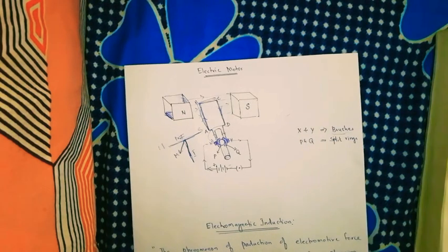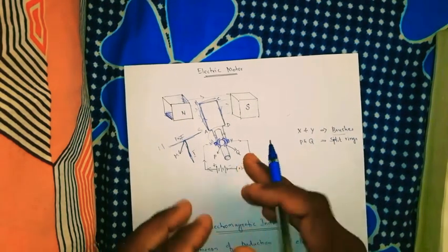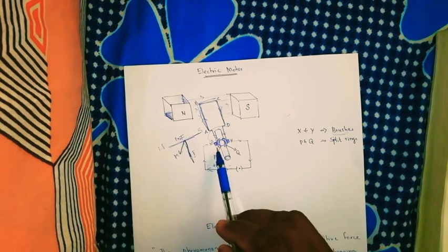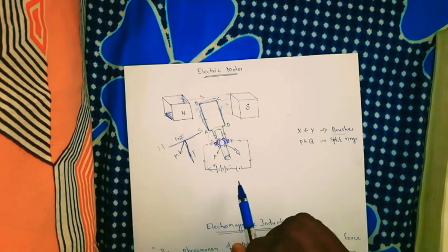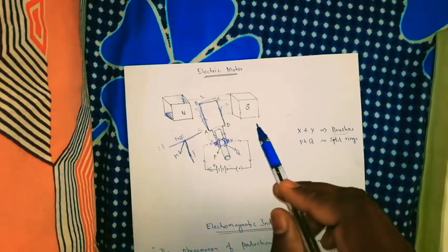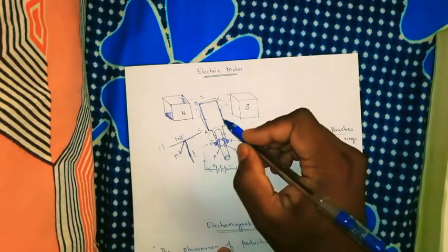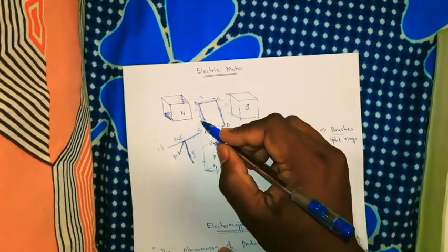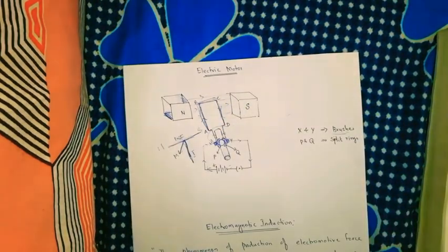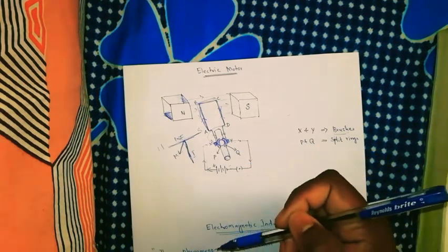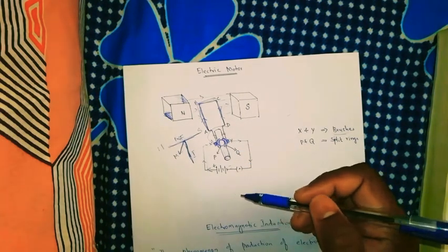Can you understand it? Here what happens? Off rotation, Q makes contact with the X brush and P with the Y brush. Therefore, the current in the coil gets reversed and flows along the path DCBA. So it goes in reverse. A device that reverses the direction of the flow of current through a circuit is called a commutator.